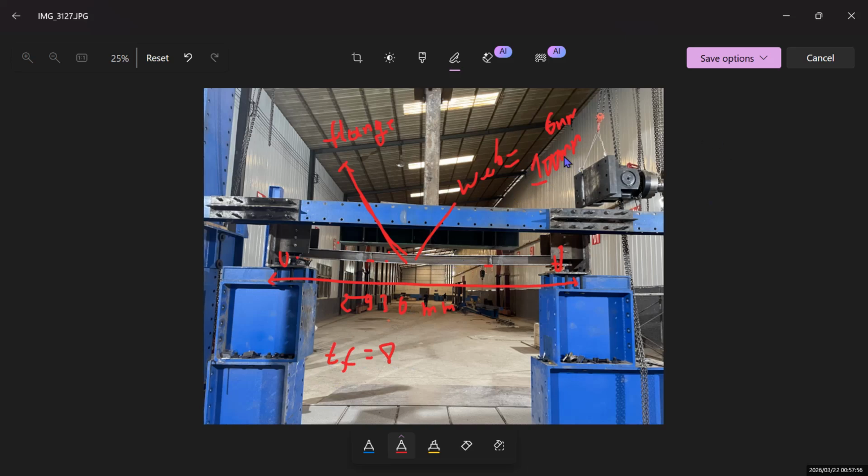In simulation, we're gonna take 100 millimeter. But when you're designing, you have to know the height between these. The height of the web is 100 minus 8, minus 8, so minus 16. I mean, 100 minus 16 is 84. So it's gonna be 84 from here to here.